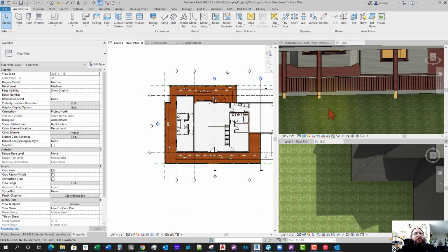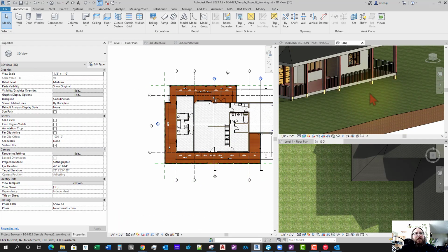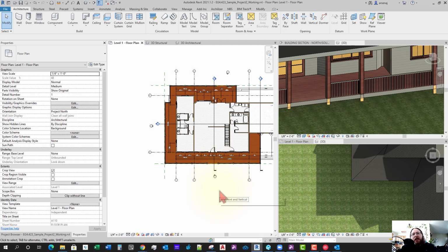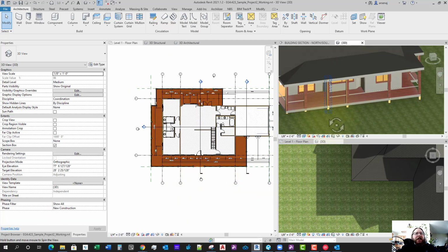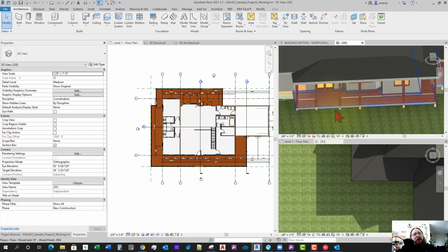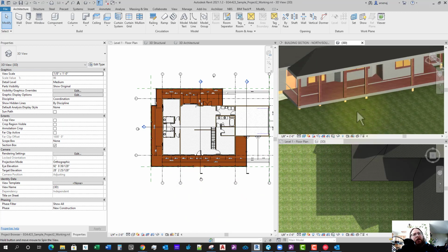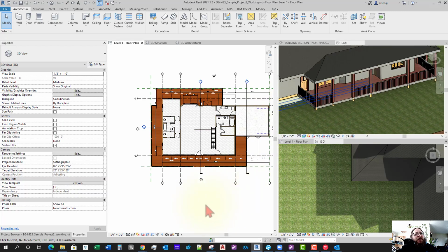So that's pretty much it for railings. They're pretty easy and pretty easy to modify. The other option for railing is, if you've already placed a stair or a ramp, you can place the railing on those surfaces so that they'll align with the slope. So the next thing we'll do here is add a stair. And actually, before we do that, no, I'll go ahead and do that now, I think. So yeah, let's just place a stair.